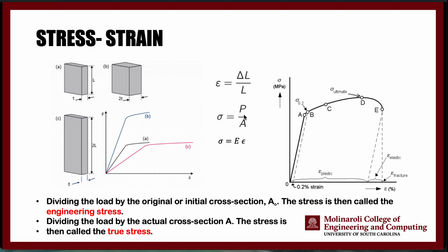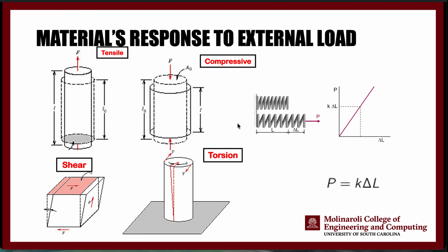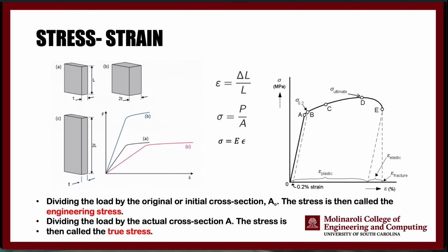You want to keep in mind that as you are applying the load, as we saw in the previous slide, your area is going to change, especially in the plastic region. So when we use the initial area for our stress calculation, we are calculating the engineering stress, which is the case in our lab, right? But when you keep track of the area and you use the real-time area for your stress calculation, you are calculating the true stress.